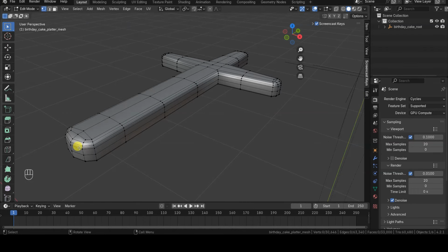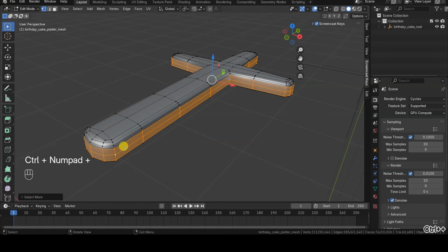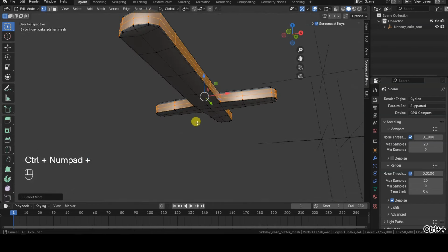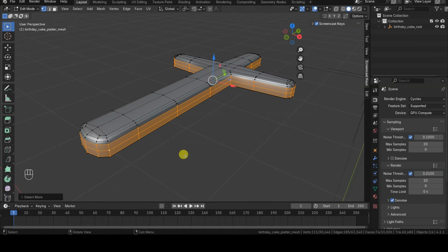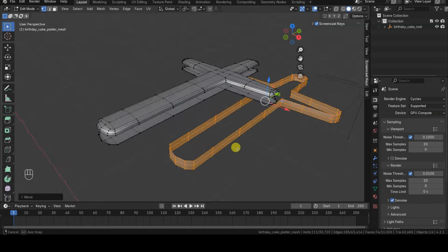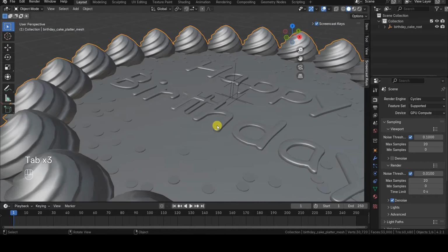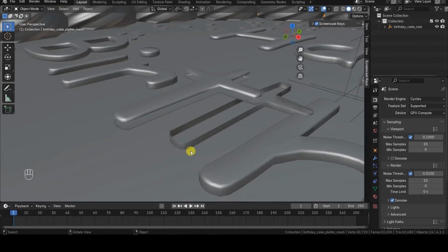Let's go back to the split operator, because its behavior changes when used on a selection that includes faces. In this case, pressing Y will detach the selection from the rest of the object, but the boundary vertices will remain in both the original and the newly created part. Here too, you'll need to move or transform the selection in some way to notice the difference. With both split and rip, the copies of selections or the separated parts are still part of the original object.